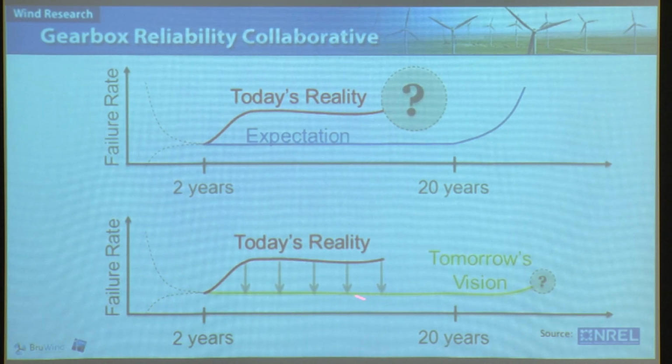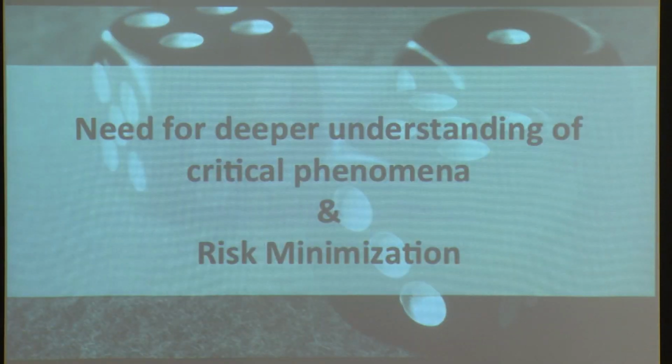What we actually want is this. If you want to reduce the cost of wind, you want to be able to use it longer than its original 20 years. You want to refurbish some stuff, put in new bearings in the gearbox, new bearings on the blades, so that you know, okay, I'm good to go for 5 more years, because that's really bringing in money. You already have the asset, it's there, and by making some tweaks, you can use it longer.